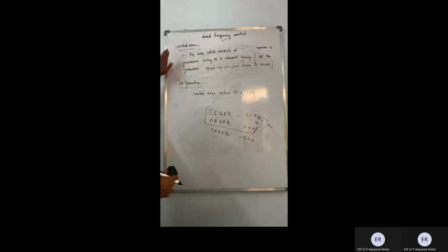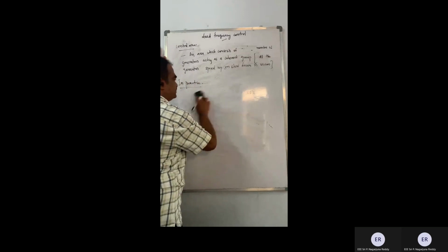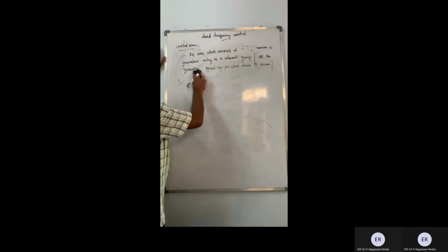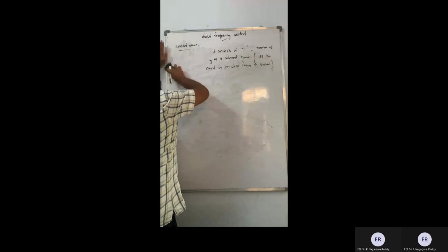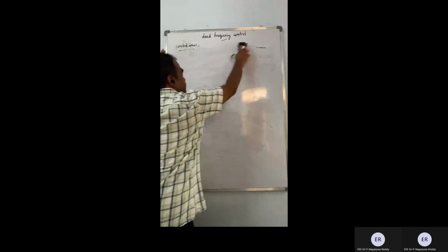Okay. What is the purpose of maintaining a control area? Because we need to maintain the frequency constant. We need all the generators to undergo the same procedure, or at least similar procedure, in order to maintain a constant frequency in the premises of that particular area.